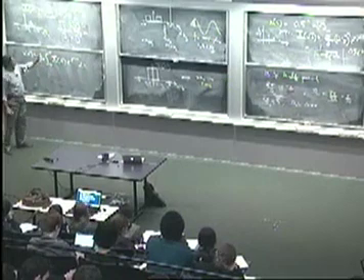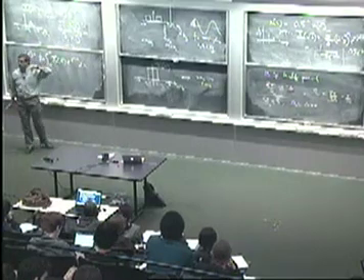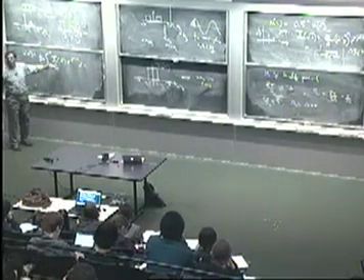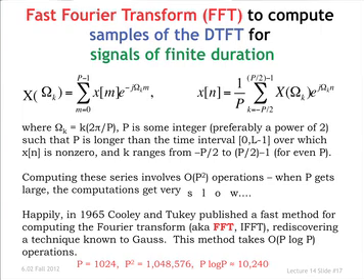What's interesting, though, is it turns out, and you might expect this, since your signal takes non-zero values only at p points, you only need p samples of the DTFT to get an exact reconstruction. And here is the formula. And the derivation is not hard. I've omitted it here. It's the same kind of idea that we used in the full case. But you can actually, using the values of the DTFT at these grid points, reconstruct the signal x[n]. Okay? So, with these simplifications, you actually have a simple pair that gets you through the numerics.